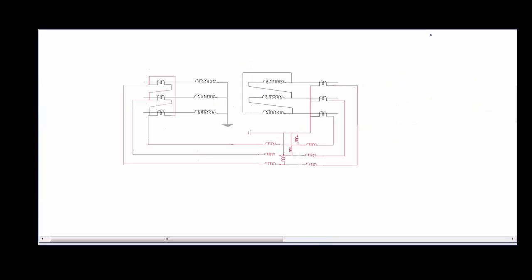So taking our discussion to the behavior of differential protection relays for three-phase transformers, I have just drawn a simple three-phase transformer in which we have the primary winding connected in star, and the secondary winding connected in delta. And talking about the vector group of the transformer, well, you can watch my video on vector groups in three-phase transformers, but in this video I'll just find out the vector group of the transformer, and it will be something like this.